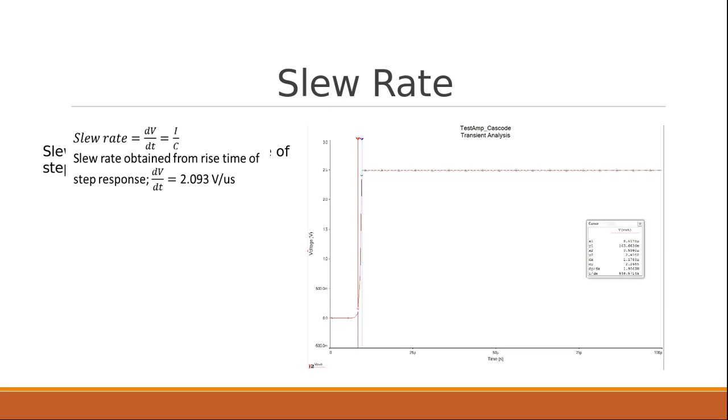Here we measured the slew rate. The procedure for measuring slew rate was basically a step response. We passed in an ideal unit step, and we measured the rise time in the output. We obtained a satisfactory slew rate of 2.093 volts per microsecond.